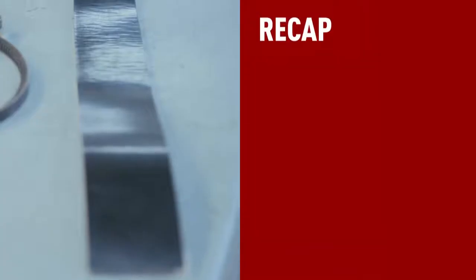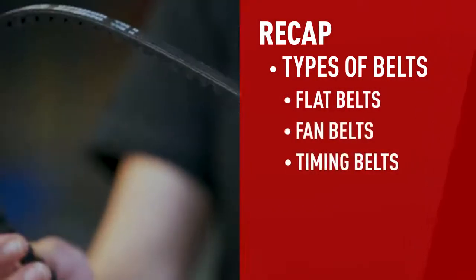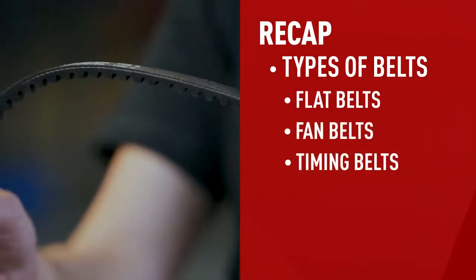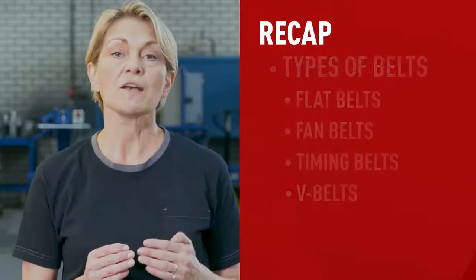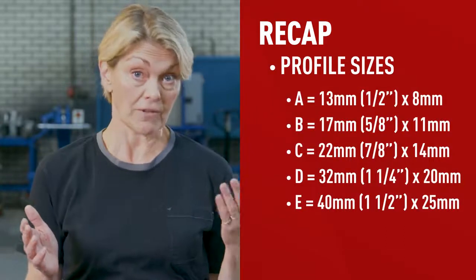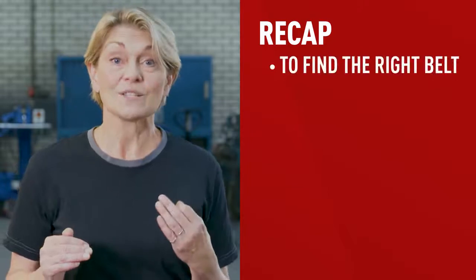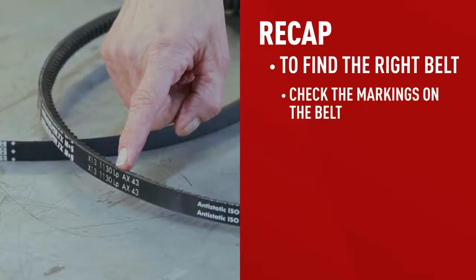Let me summarise what I've just explained once more. We talked about flat belts, fan belts, timing belts, and, most importantly, V-belts. They come in 5 different profile sizes, A through E, and can be either cogged or standard. To find the right belt, the easiest way is to check the markings on the belt.